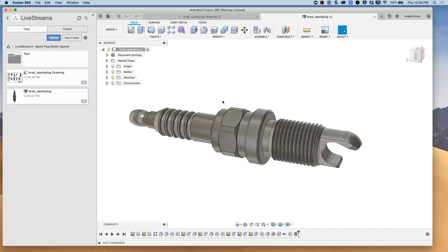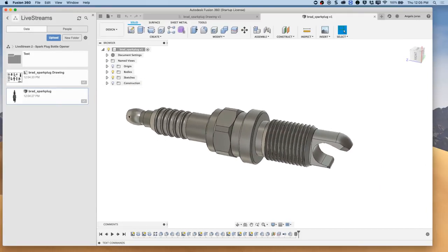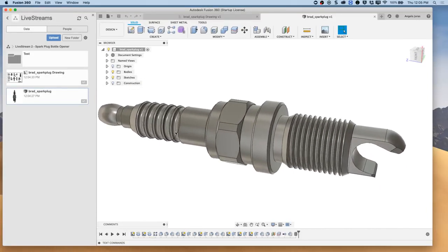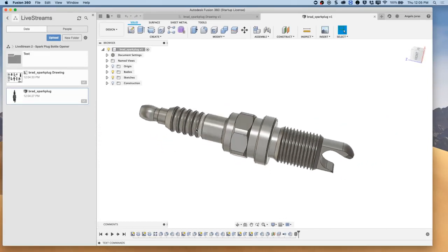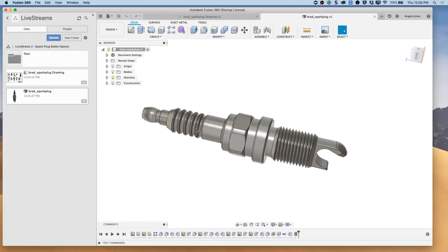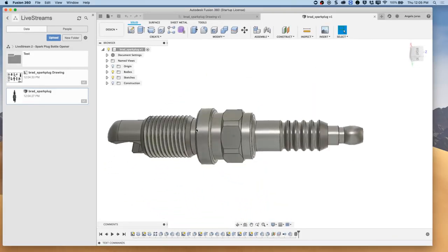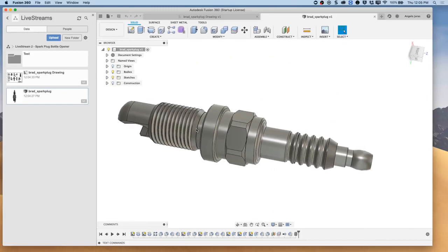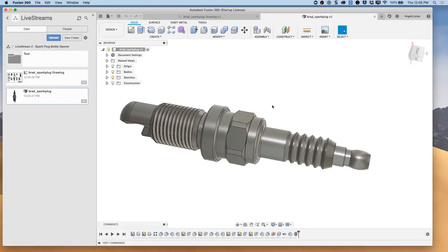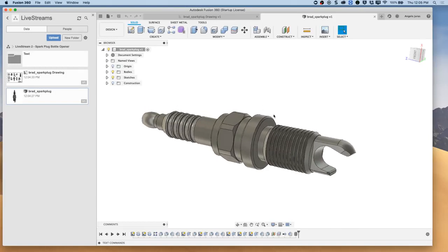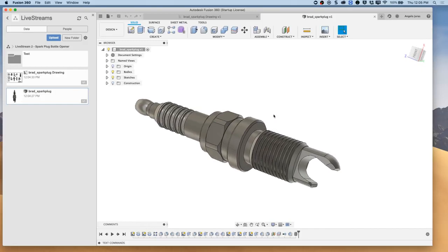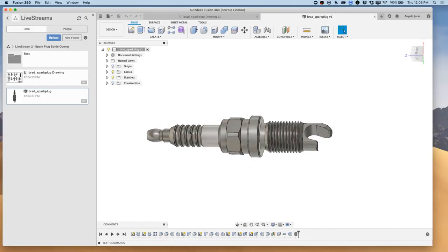So what I do as a machinist, anytime I'm making a part, I'll review it and take a look at it, get some ideas. I start thinking about how I am going to hold it, what operation I'm going to do first, what machine I have available. That always makes a difference with how you're going to approach it. So what I'm going to be doing this on is a Haas ST10Y, and that's a machine we have at Pier 9. And so already I'm thinking that I can hold it in this orientation, so I'll chuck it